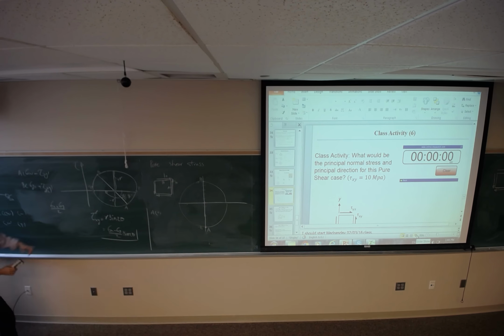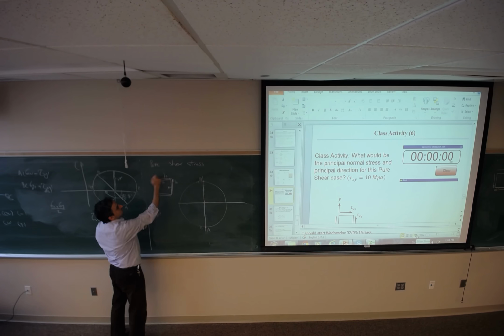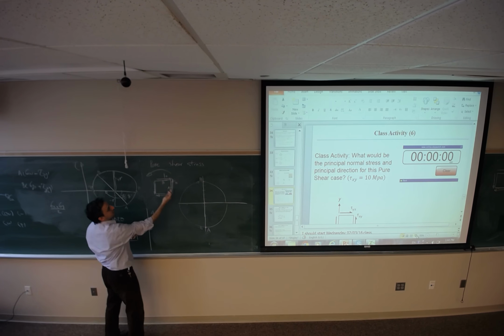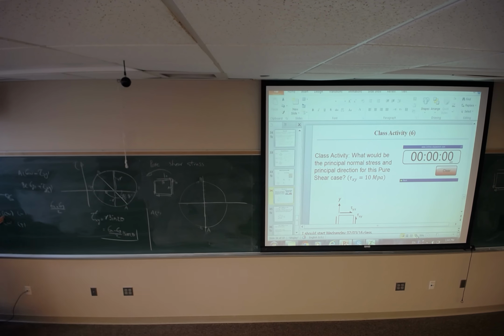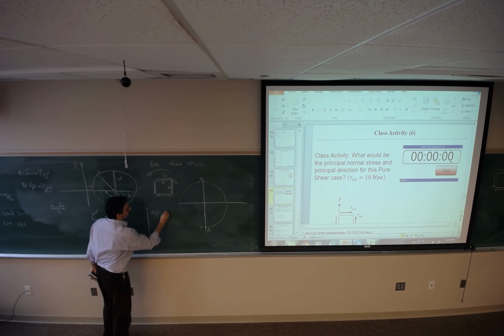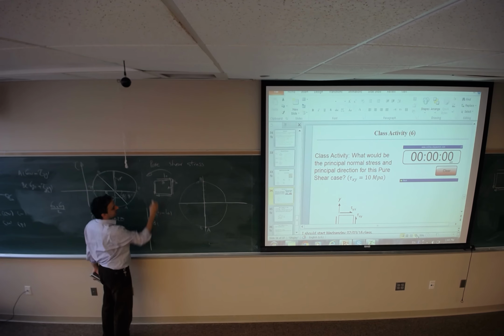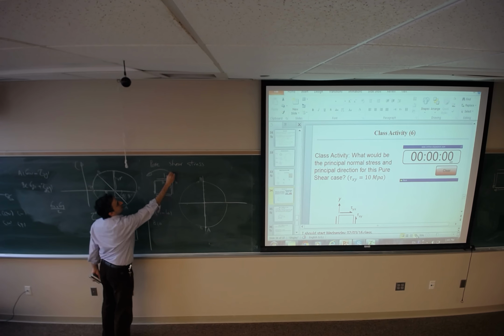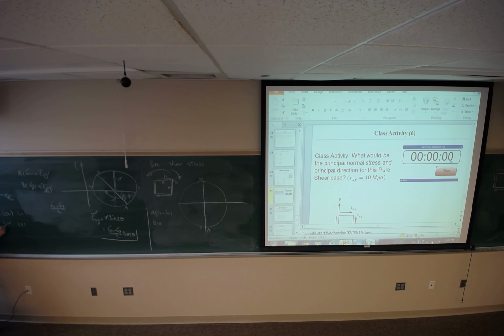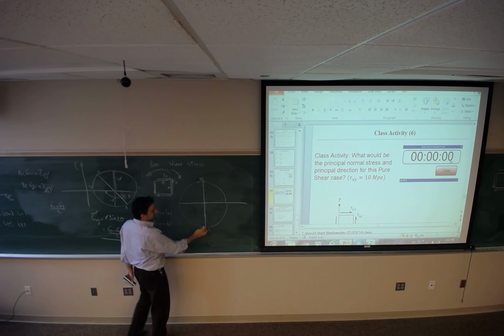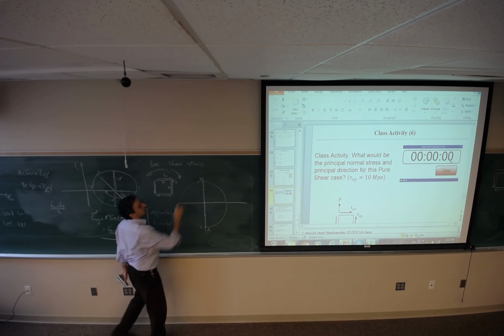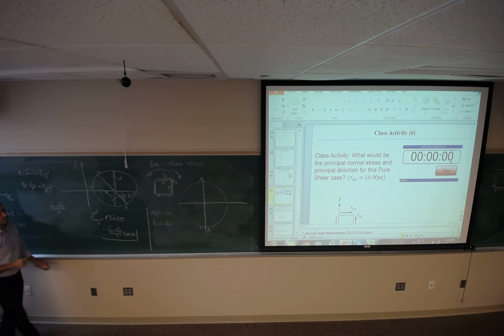But for the shear stress, it is making rotation on this square in the counterclockwise direction, and in Mohr circle, counterclockwise is negative. B doesn't have any normal stresses, but this one is making rotation in the opposite direction, which is clockwise, and it's going to be positive 10. So point A is going to see 0 and negative 10. Point B is going to see 0 and 10.